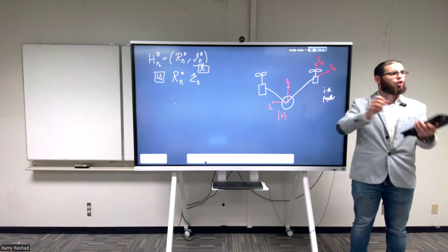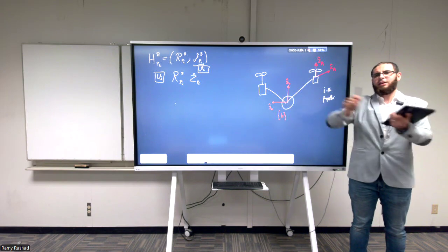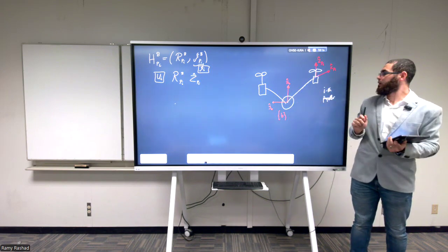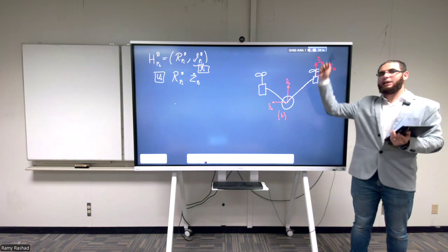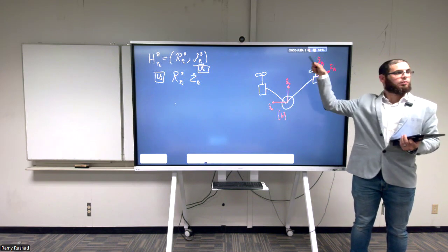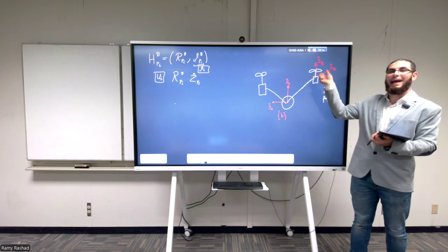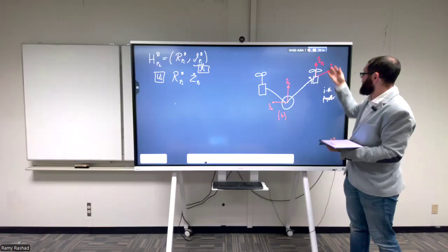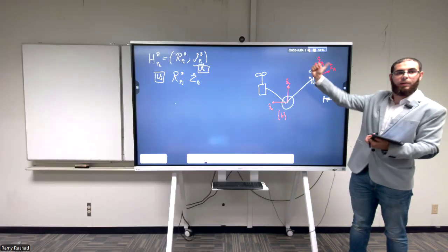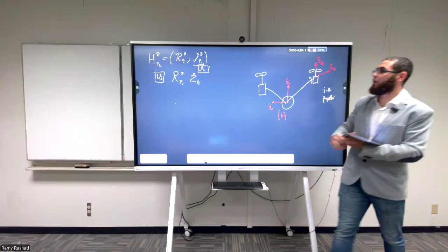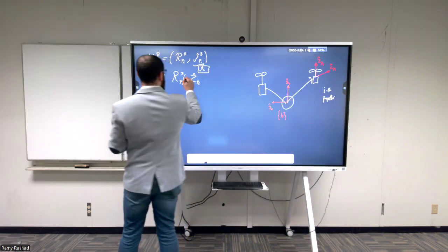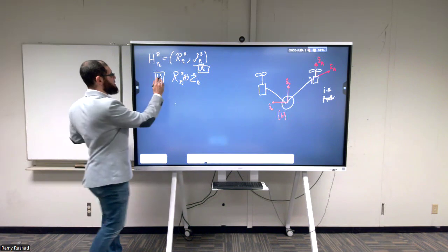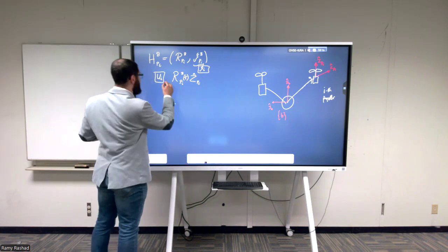We're not considering drones that have prismatic joints or are moving around. While the orientation can change, because it depends, for example, on whether you have an extra actuator that tilts the propeller in this direction. So in general, this rotation matrix will be a function of time, and this u_I will also be a function of time.